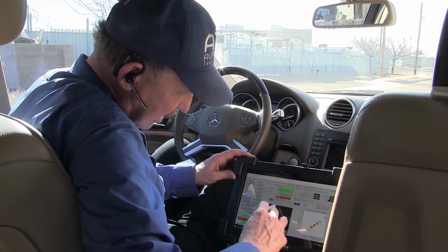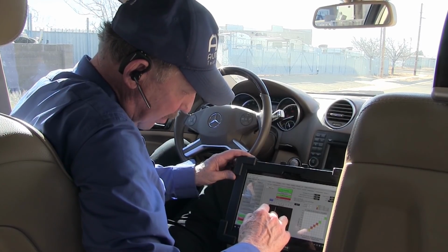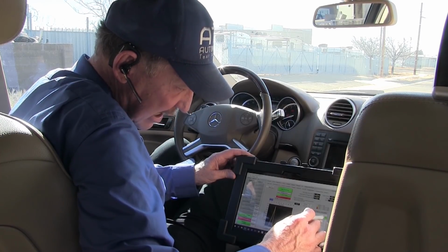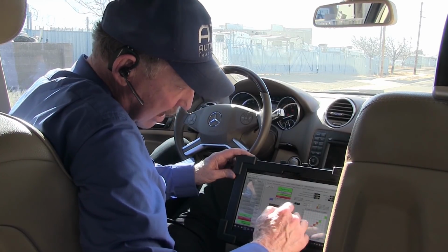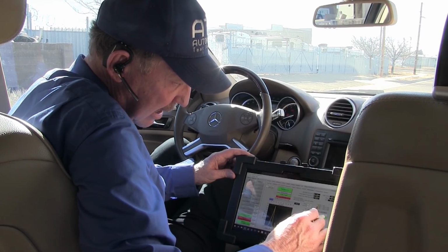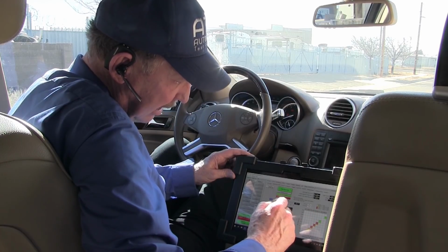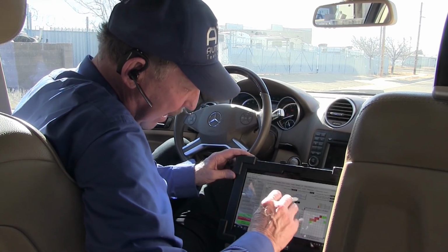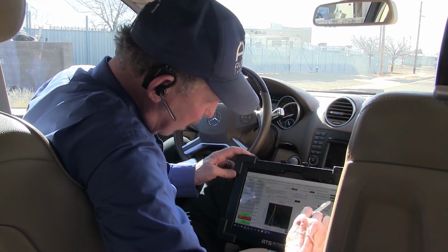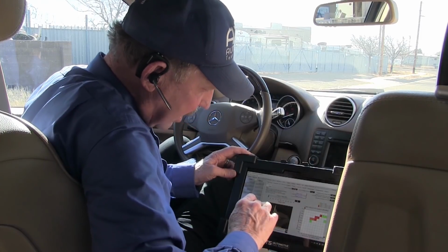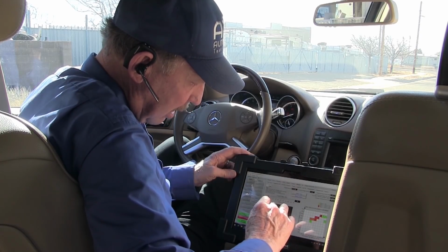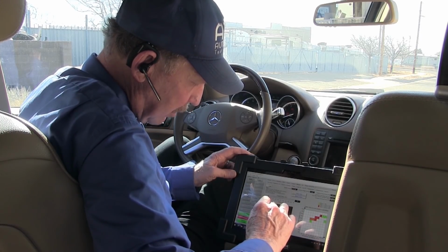Okay, so we can see the yellow trace is actual reading and the red is what our MAP should be. They're really close. You see how they're fully open, they're green, they're good, and we're off a little in the middle, but we have big trims up top and on the bottom, and this is saying we're okay, except for right in the middle, we separated a little bit. Now, to get a better idea, go to power, and the power is given right here, and we're going to match horsepower. Now, the horsepower is matching it wide open, so the overall air going into the motor can make the right amount of horsepower. So the air is being read right.